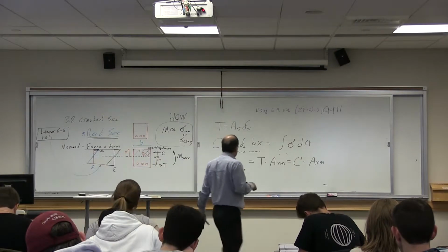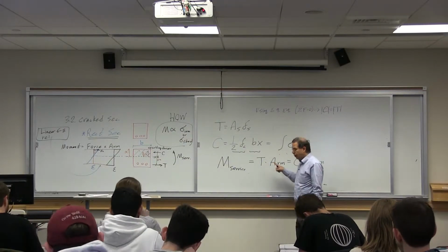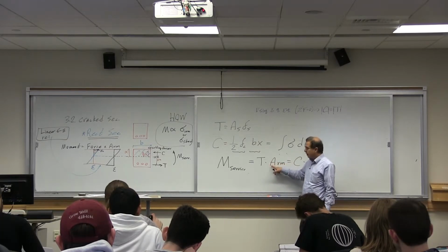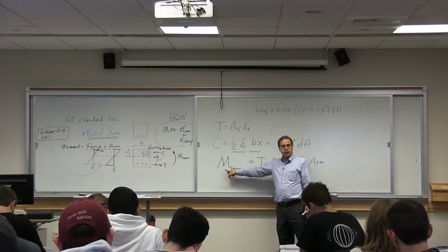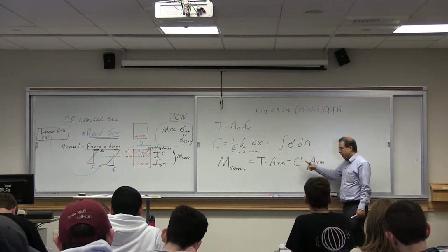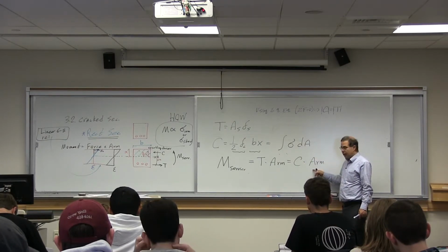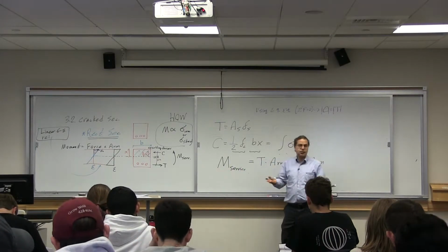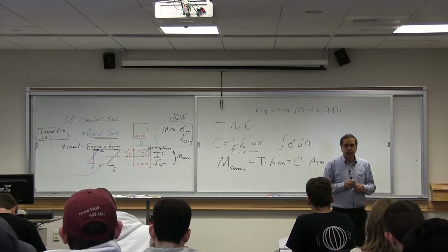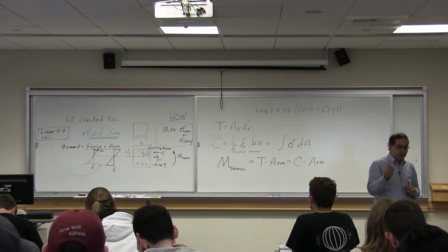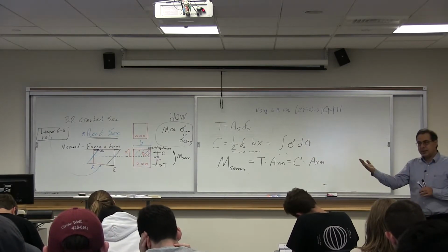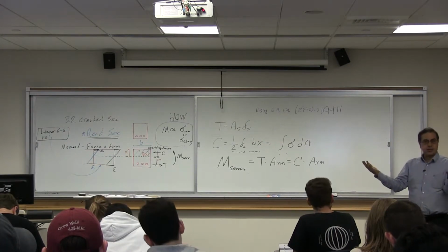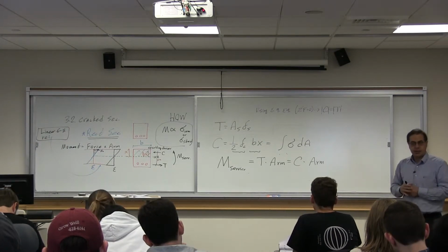If you use tensile force times R, you find a relationship between rebar stress and the moment. If you use compression times R, you find a relationship between concrete compression and the moment. Those are the things we were looking for: the relationship between moment and stress in concrete, or between moment and stress in the rebars.